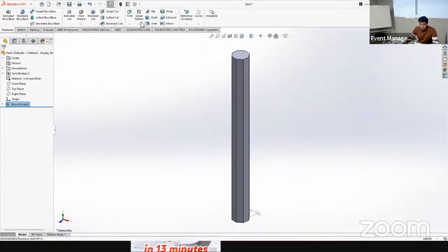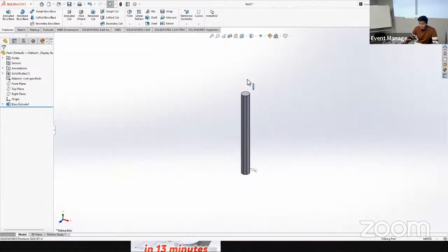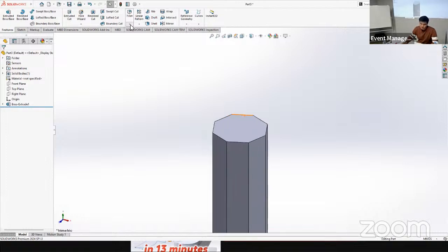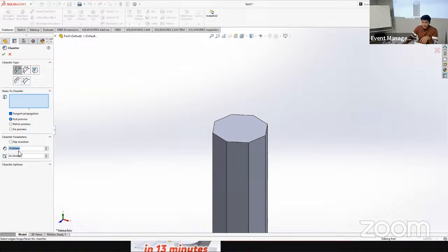Okay, and after that, this part should be pointy, conical, or in our case, we can just make it by using chamfer. It gives us the length of our chamfer cut and also the angle. If you imagine this 90-degree place, chamfer is like cutting it at some angle, and it has two properties: this length and this angle. To make it more pointy, let's make our angle like 60.